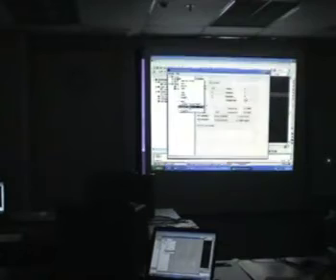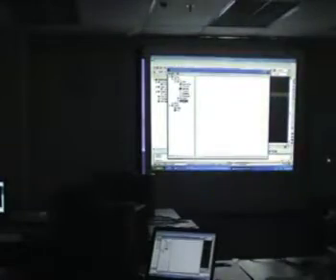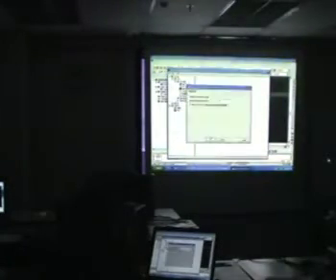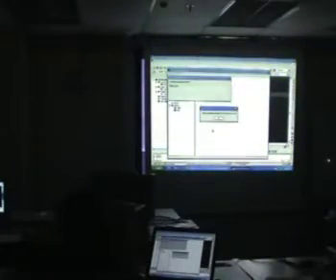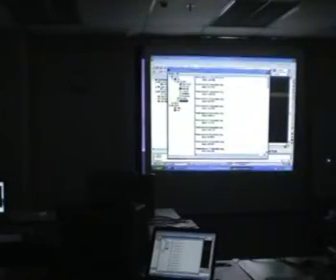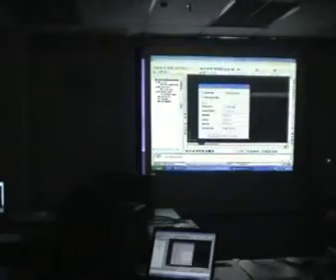You just right click and... not right click. You open up OGL, you go to watershed and you right click on watershed and calculate watershed. This basically calculates the catchment areas of the surface. So you can see all these watershed IDs. If you want to put them into the drawing, you just click import watershed boundaries.